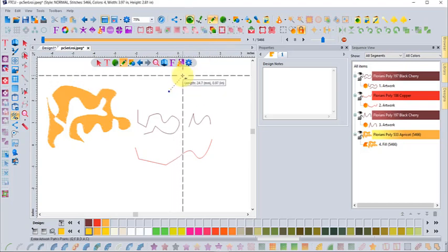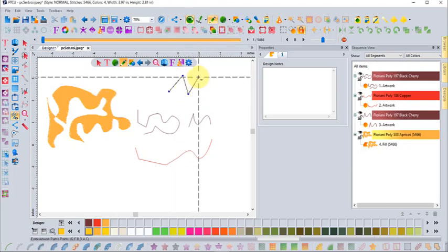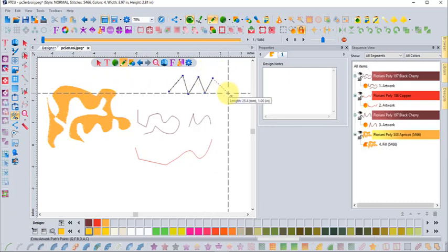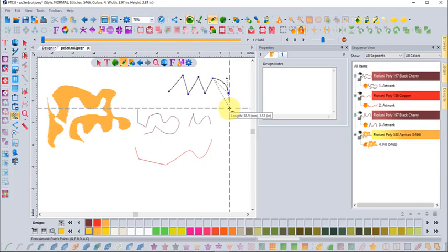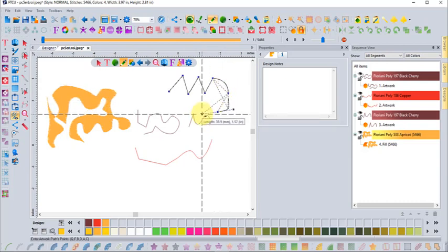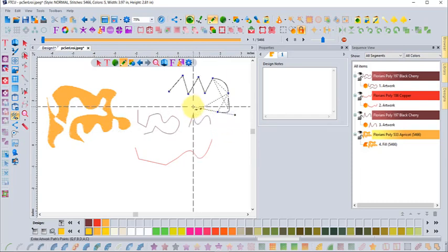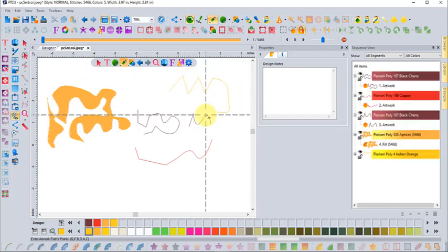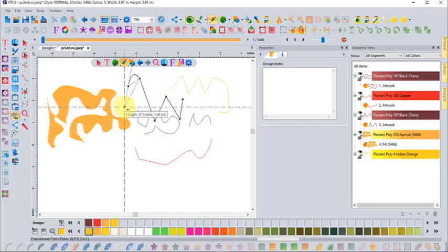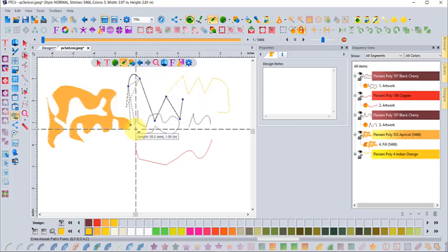Bezier is like the first one in that when I left click, I get a corner. But with Bezier, I can left click and drag to create a curve. If I left click and drag, I continue to create the curve, and when you right click, it stops drawing. So left click to draw, left click and drag to curve.